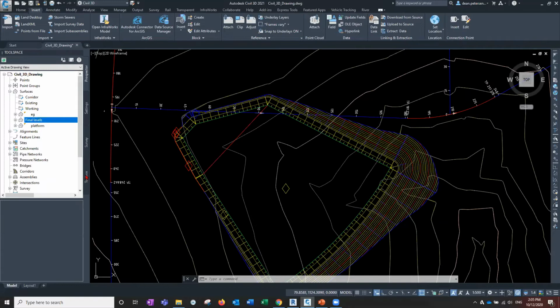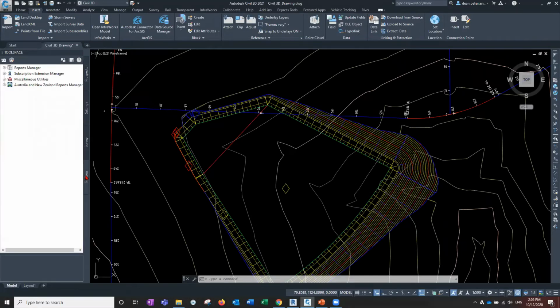For Civil 3D, it's an extension that you grab. You get it from the Autodesk account page where you download your software from these days, or your IT people may download that. In there is a whole bunch of extensions. This is one of them. It's called the, if I open this up, Shared Reference Point Extension.